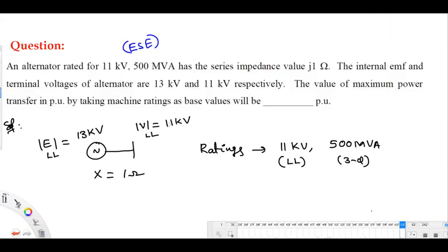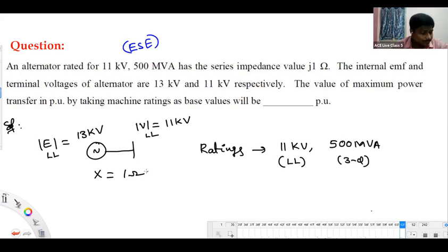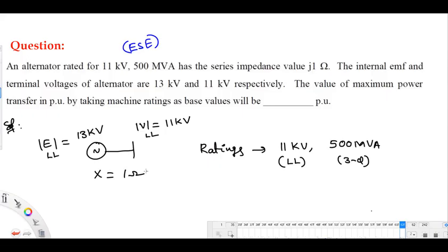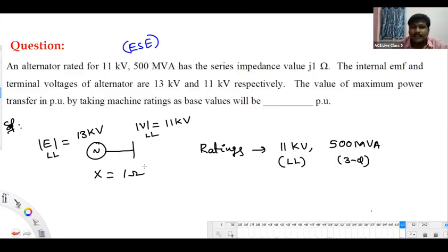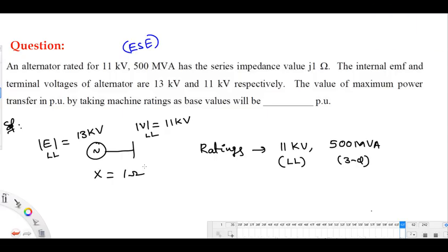Sir, in a transmission line, I have observed that each phase consists of 2 lines which run along with each other with a small gap between them. That's a bundle conductor, not a double line. Bundle means more than 2 conductors in each phase, but very close to each other.